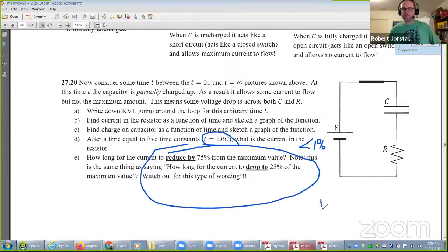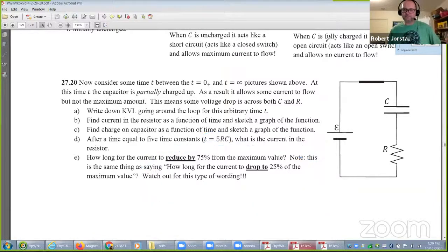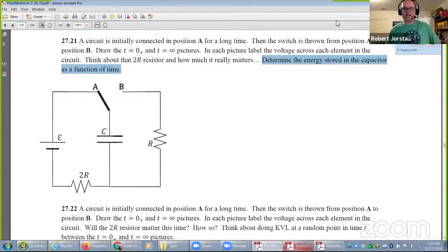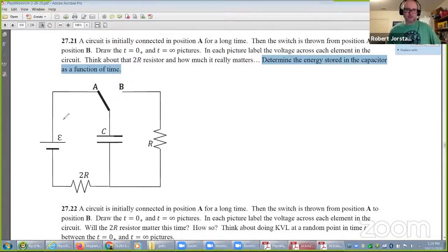We learned there's a trick where you could take the logarithm to get the exponential out of there. All right, that's good. We learned that you can have different time constants when you're charging versus discharging, right? So here, tau charging was different than tau discharging. They're not always the same.